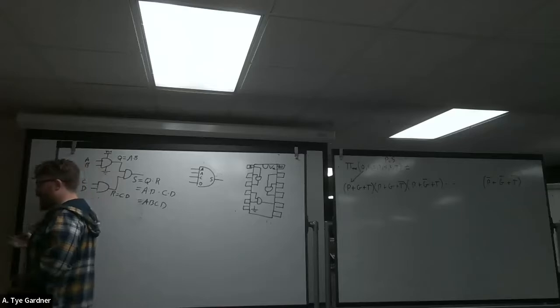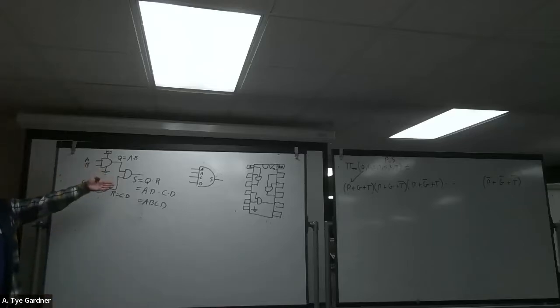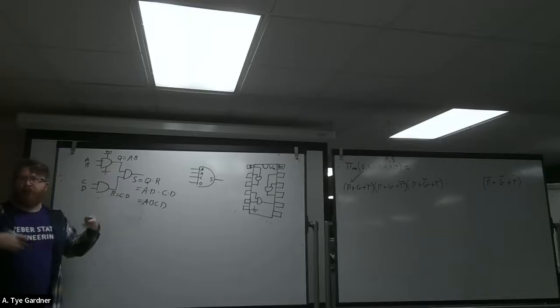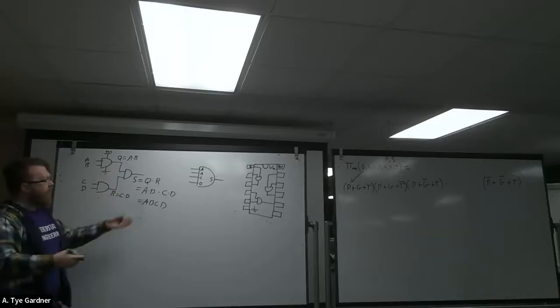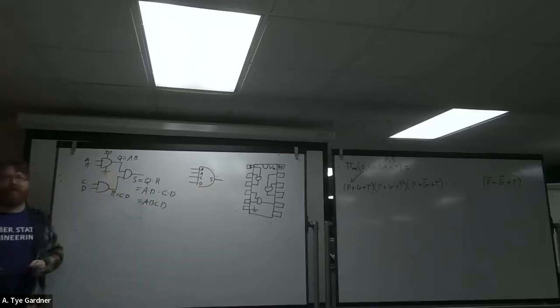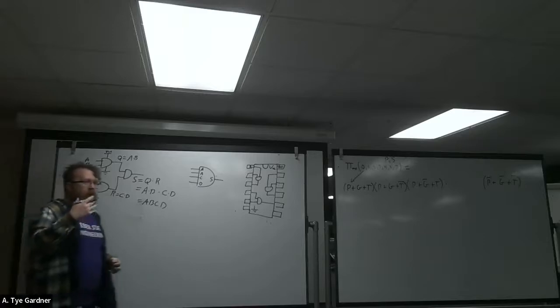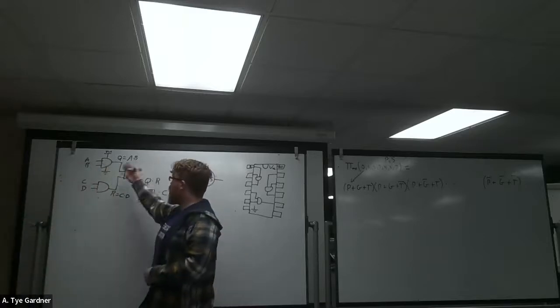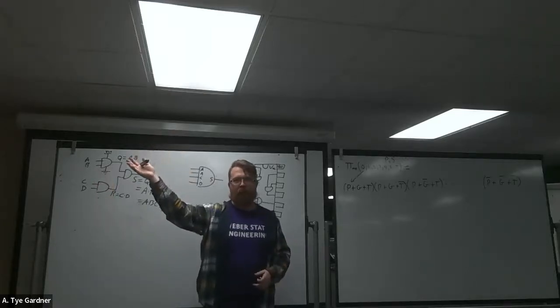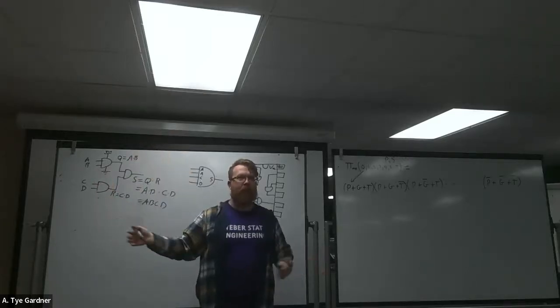So when I call this a 4 input AND gate, I mean this, okay? And this is why when I say intermediate signal, Q, R, I will also call them internal signals because they are inside of this. They don't leave. The outside world does not know that Q and R exist because they don't need to, right? So they're a local connection. So if I had within the circuit something else called Q, it must be connected. But when I go to a higher level of abstraction, it doesn't need to know it's there, okay?